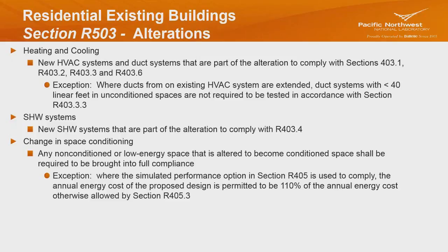Now there are interpretations that you can look at, because additions can be when you're adding new conditioned floor area. And let's say that garage that you're turning into a family room, is it an alteration or an addition? So pay attention to what your project is doing and what's happening and what provision it really falls under, whether it's an addition or an alteration.